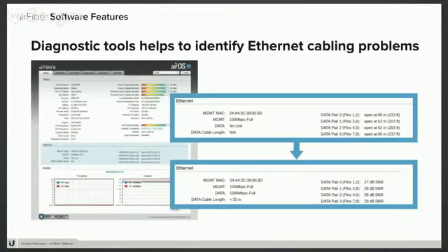On the cabling side, one of the things we've learned is that when you look at a large network, one of the most common problems you find turns out to be issues with cable. And unfortunately, running long runs of outdoor cable up and down towers is no different. So what we've done is integrate a time domain reflectometry system that measures and rates the quality of your data link cable.